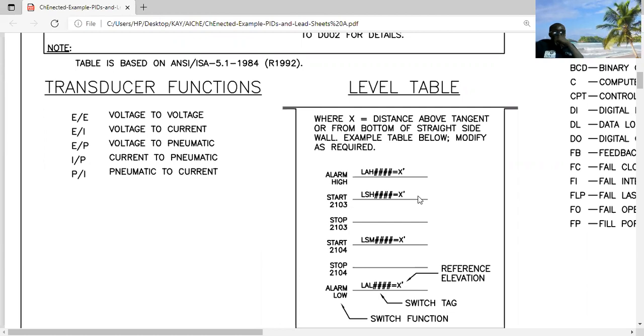The alarm will switch on when it sees that the level has gone below the level you set it to be. That is, if it has gone low, the alarm will trigger that this level has gone down drastically. Then the response from our control valve, the LC, which is controlled either pneumatically, hydraulically or electrically, is that a signal will be sent to that valve to give a command, because the alarm has already triggered. So it will listen to the alarm.